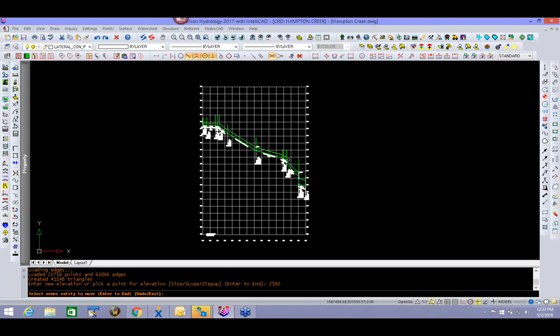I draw all of my storm drainage and my sanitary all in one profile, so that when you see mine, you automatically are checking for service clearance. In this case, when we do lateral check, or when we do crossing checks, it's only at the crossing of the pipes. You still have to know, if you've got to come out of the top of a sewer line with a service that goes at 1% underneath storm drainage, you still have to modify that yourself and watch that yourself. But I'm working on it.